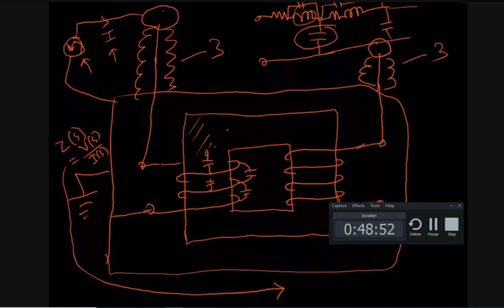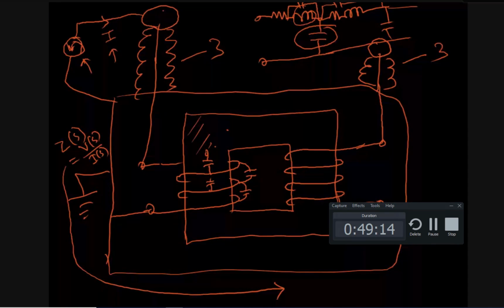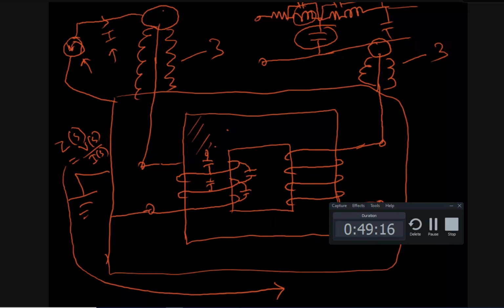And if there are changes, and at which portion there are changes, based on that I can even estimate the location of the damage inside the transformer, exactly where there is a problem. For example, in a transformer, what kind of damages can you expect? For example, under short circuit conditions, during faults, what kind of problems will be experienced in a transformer? Do you have any idea? Turn to turn fault, sir.